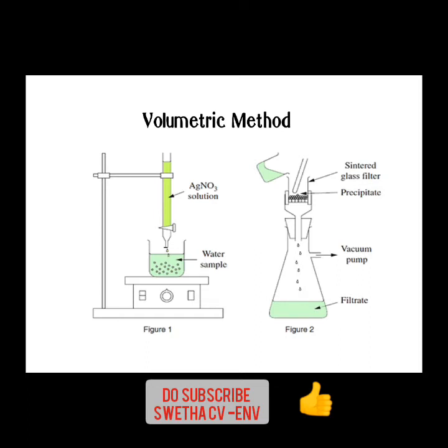The second is the oxidation and reduction method. Here, in analyzing a sample, they supply a measured quantity of oxygen to know the concentration of the pollutants or the quantity of pollution present in that sample. Either you add an indicator or you don't, because for some the end result is shown directly by color change, and for some they add an indicator. So it is not mandatory to add an indicator here, whereas in the acidity and alkalinity test, you need to add an indicator.